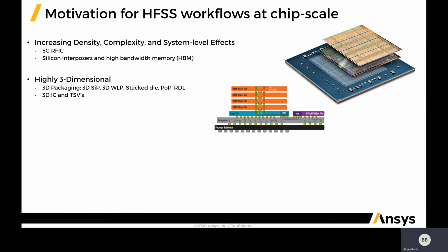A lot of this is also being driven by packaging technologies. So as people have moved more to 3D packaging, be it stacked dies, broader use of redistribution layers, wafer level packaging, and so forth, we get more density in three-dimensional space. And this often requires a three-dimensional aware solver. We're also seeing an emergence in 3D ICs and TSVs.